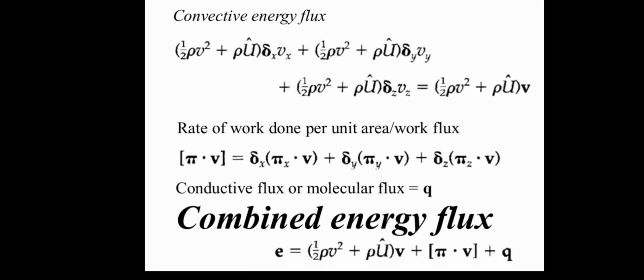Now we consider some specific examples such as flow of an incompressible Newtonian fluid between coaxial cylinders. In such cases, the rotation of one cylinder relative to the other causes viscous dissipation within the fluid, leading to a temperature profile that is influenced not only by the boundary temperatures but also by this internal heat generation.